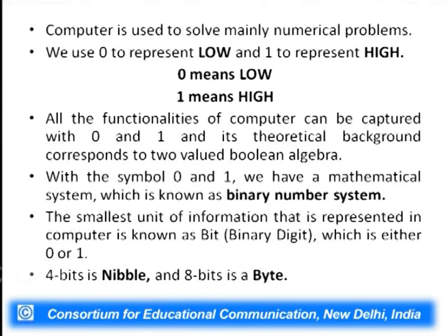The digital signal, on the other hand, is also referred to as a discrete signal. This signal has fixed definitive values that it will take. So we already know which of the values in the set it is going to take. The exact value may not be known, but we know that out of these values, one discrete value is what this digital signal is going to acquire. Now digital signals are usually represented as a high and a low signal. Usually the low is represented by a logic level 0, while a high is represented by a logic level 1.